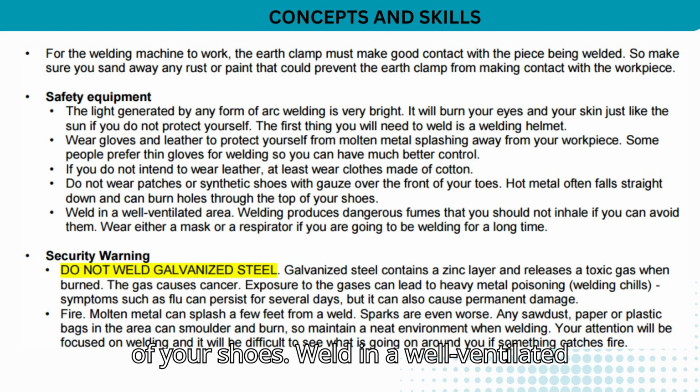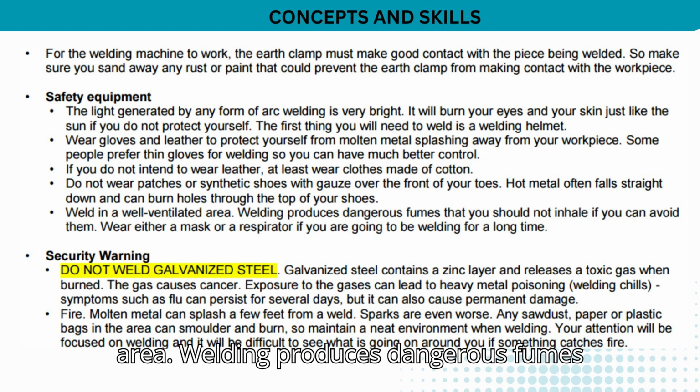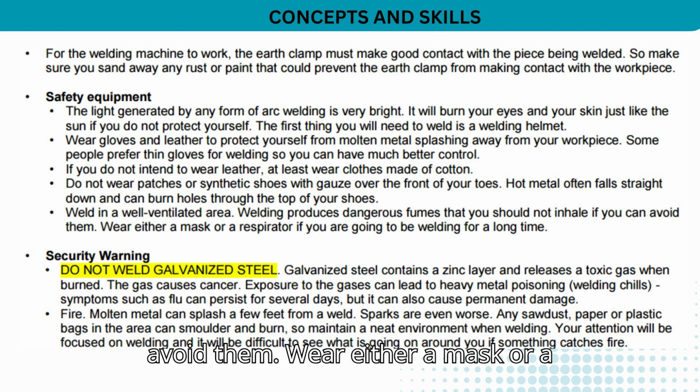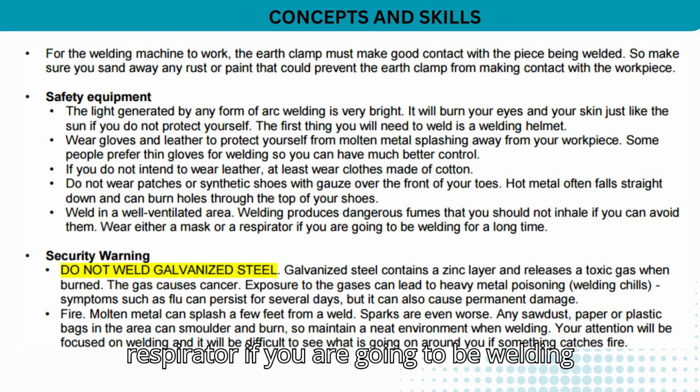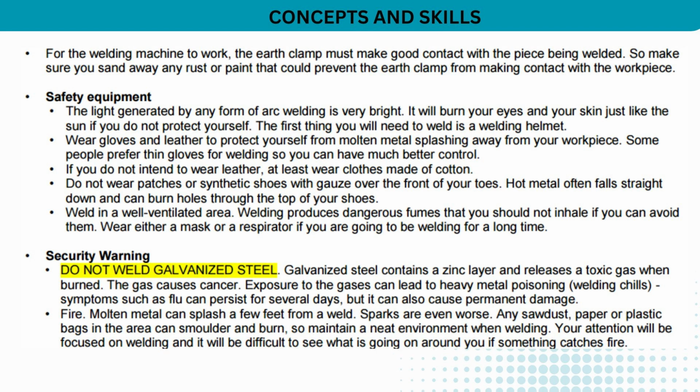Weld in a well-ventilated area. Welding produces dangerous fumes that you should not inhale if you can avoid them. Wear either a mask or a respirator if you are going to be welding for a long time.